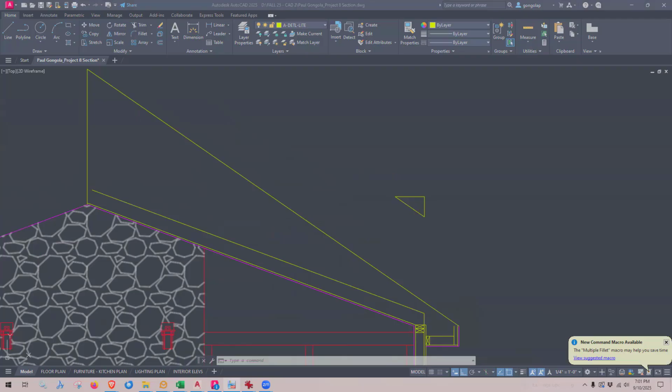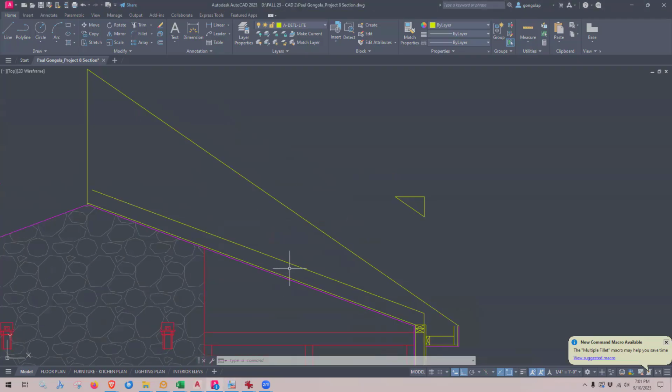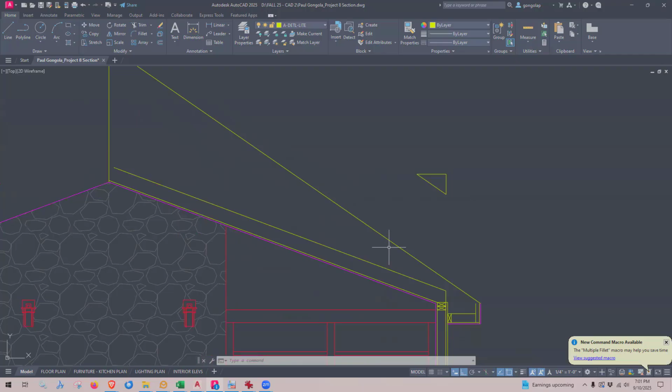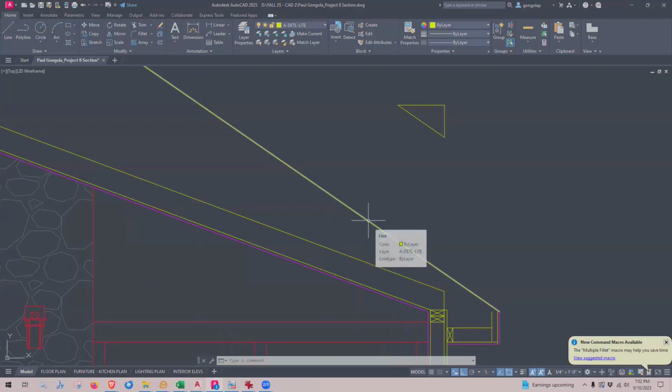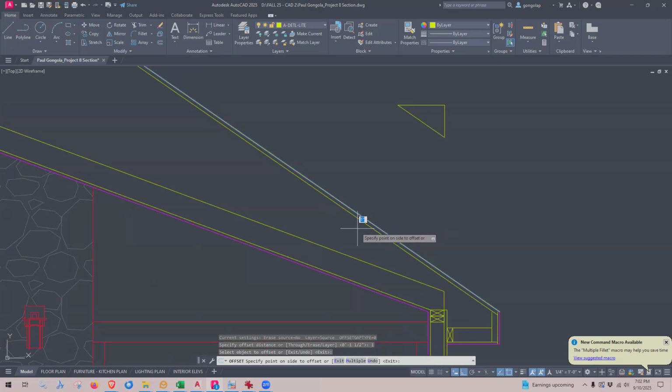So our roof joist is also going to be just like this was a 2 by 6, which was 5.5 inches. Our roof joist also is going to be 5.5 inches. But first, I need to draw some sheathing. So the roof sheathing is again plywood that's sitting on the roof joist, and then the shingles for the roof are literally nailed into the plywood sheathing. So our roof sheathing is thick. It's a full inch. So I'm going to offset my roof line down 1 inch.